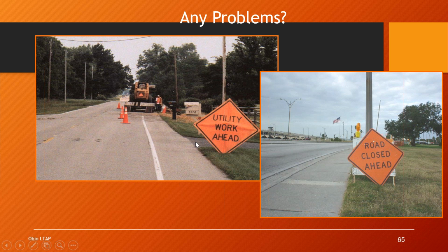And so the point I'm making is that this is a higher volume road and high speed. And so in this particular situation, the work zone that we see should not be designed the way they have it. These workers have placed themselves in a very dangerous spot, and the motorists have also been placed in this dangerous situation.